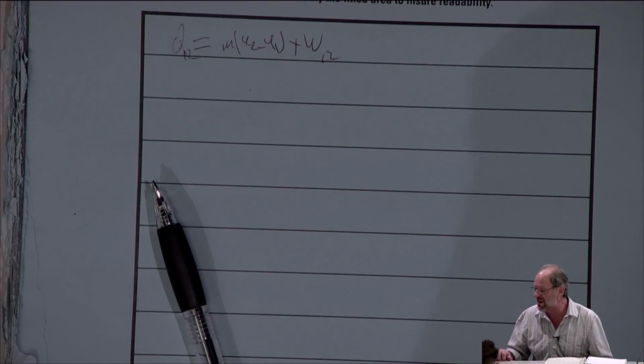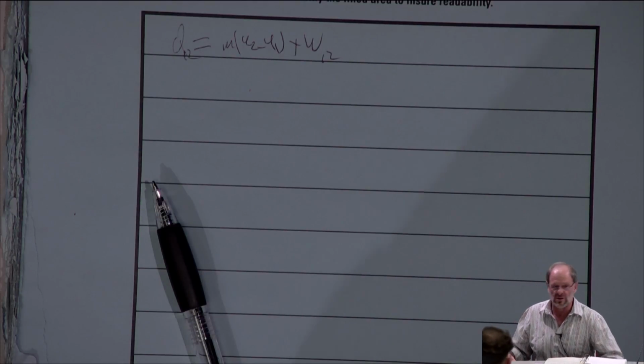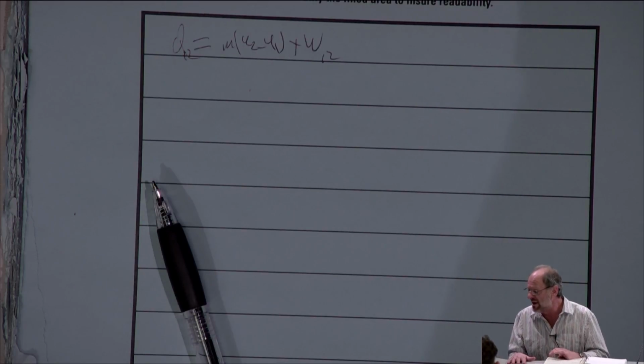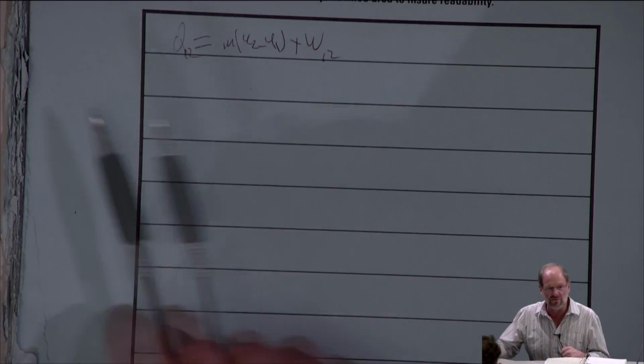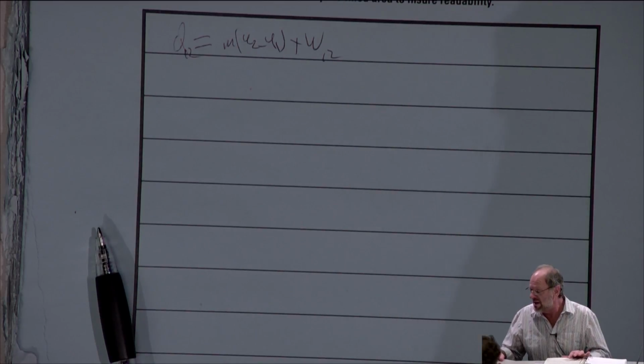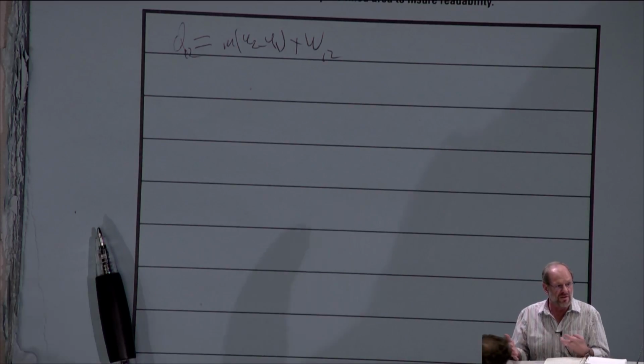You can use your logic and say, oh yeah, I know work done to the system is negative, and I got a negative sign. You're comfortable knowing that you did it right, at least that the sign is right. So that's an important thing to note: don't ever adjust the first law. Keep it exactly the way it's shown. Let the signs be whatever the signs are based upon the data of the problem.